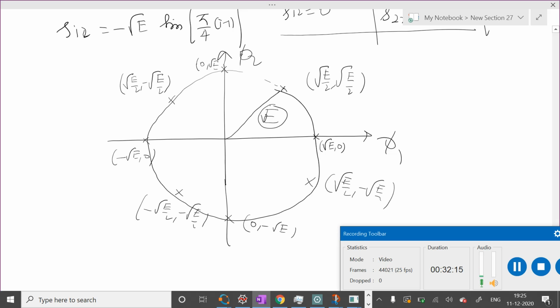So you now have 8 points. We know that 2 to the power 3 is 8, so each point can represent 3 bits. Suppose I start from this point as 000; it's up to me which bits any point represents. The next one I can represent as 001.